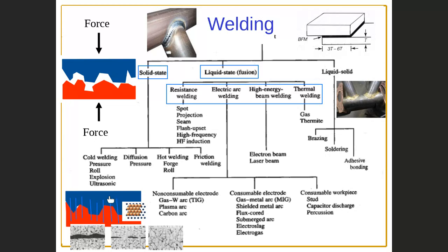So if you have different material, for example steel and aluminium, no issue. Material diffusion will happen, aluminium and steel diffusion, and finally the bond is done. This is the perfect solution. Let me tell you, solid state welding is a perfect solution to weld dissimilar material. Actually, there is a big challenge in industry in welding dissimilar material, and there is always a need in industry to weld dissimilar material. The perfect way to weld dissimilar material is solid state welding.